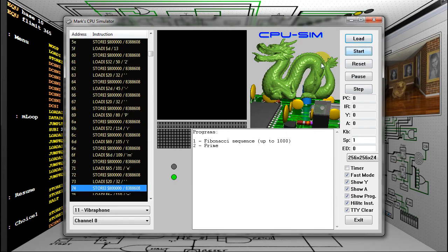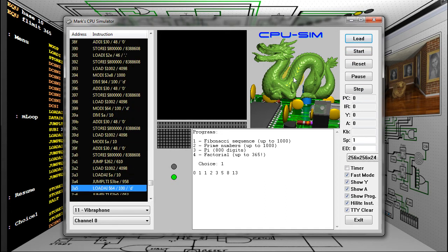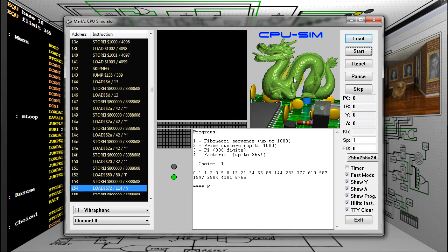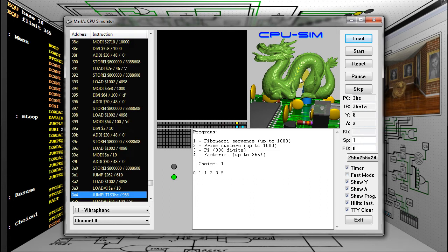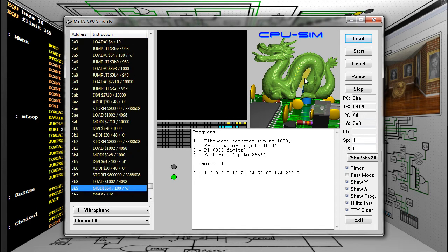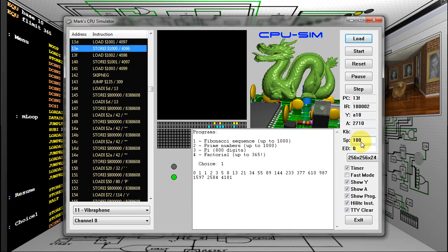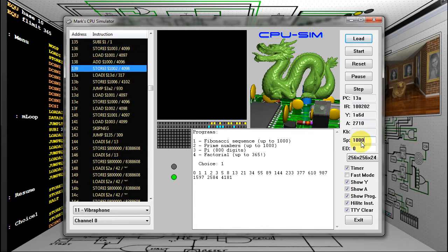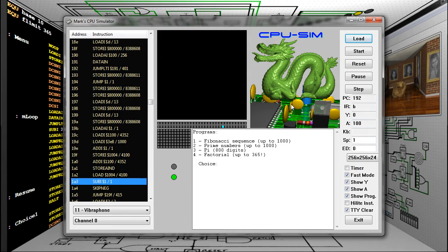If the show program option is selected, the simulator disassembles the program while loading. It's not reading the source code. The highlight instruction option highlights the currently running instruction. The show program option is off by default since very large programs can take a while to put in the listing window. The speed value changes the delay used. You might want to slow down the execution so you can better see what's happening. Highlighting slows down the simulator, so it should only be used when necessary.